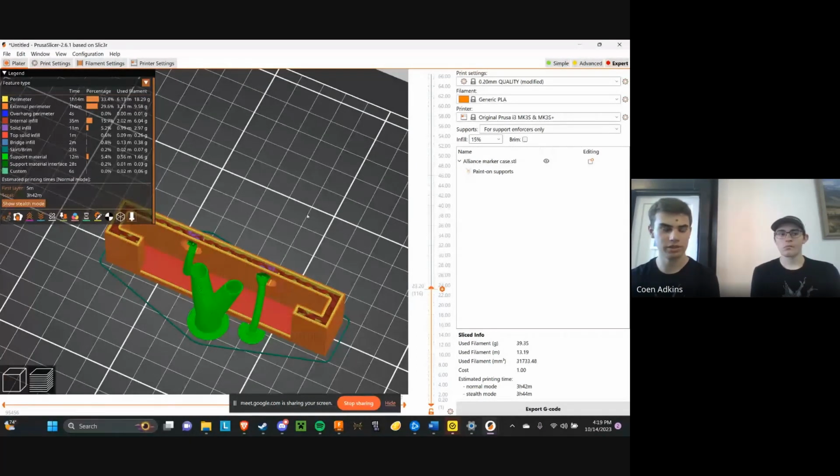And then sometimes, especially with motors, because they're pretty heavy, the off-the-shelf brackets, depending on the amount of force that's going through it, wobble a little bit, which causes some inconsistencies depending on the use case for the motor or servo. So by designing our own, we can make sure that there's no wobble in weird directions, and then we can make sure it fits exactly where we want on the robot.